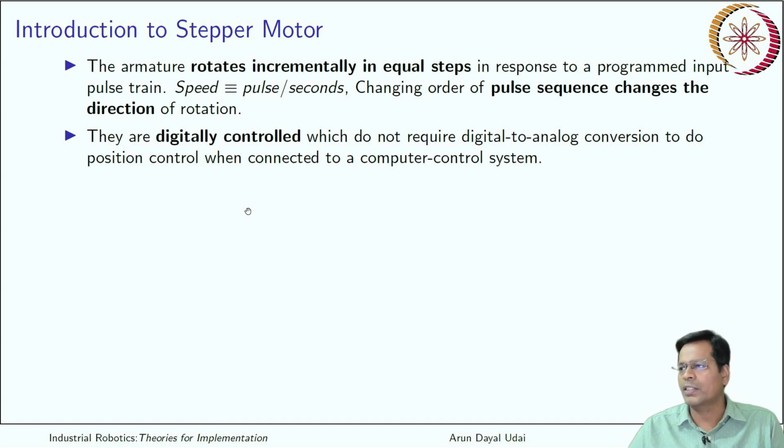That is all not there in the case of a stepper motor. Even if you want precise position control, the hardware allows you to do it without any feedback, as long as the load is within the prescribed limits and the motor is not slipping.